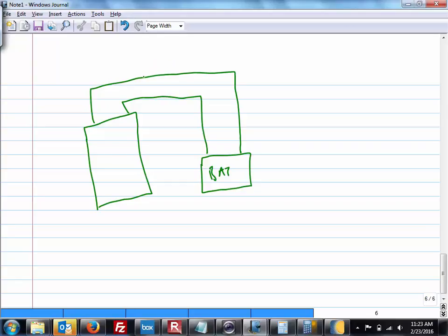Somewhere in here you would also have a load, of course. If this V array or V module, however you want to look at it, if V array is greater than V bat, you will get, well, that's what you want. You want the voltage to be greater and to flow into the batteries.